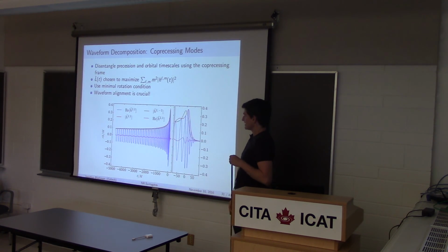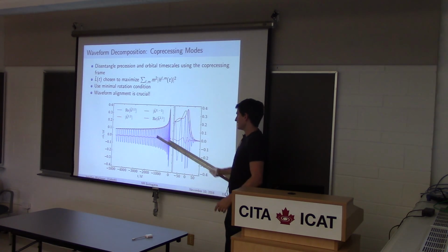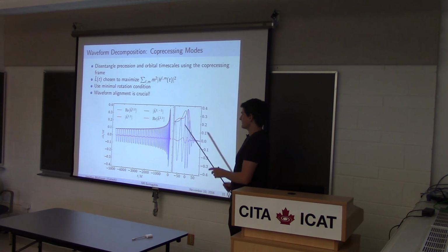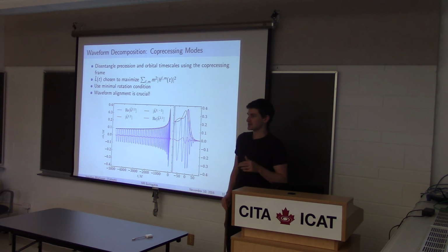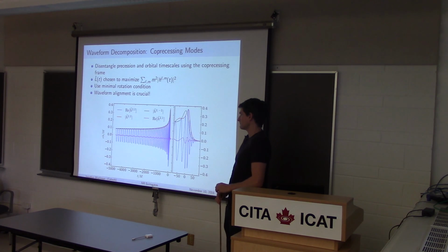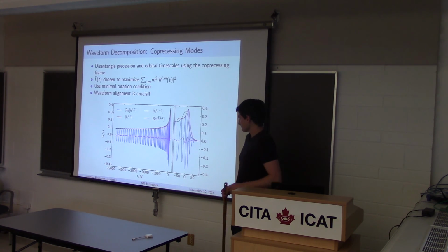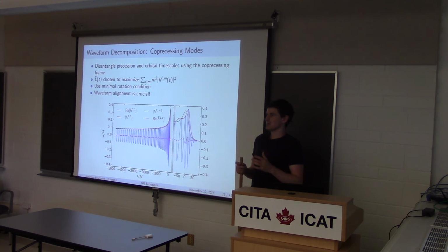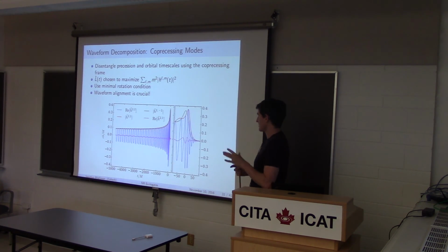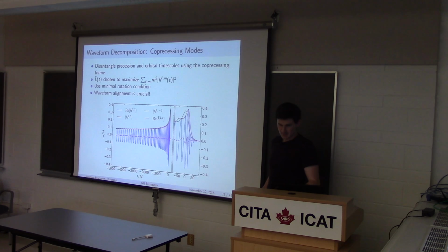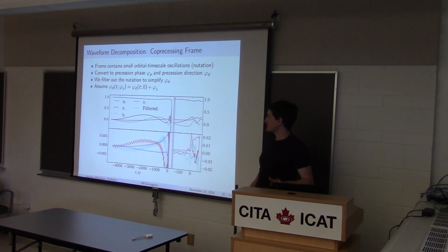smooth as well. If you take the symmetric difference, you end up with a real oscillating part. That's not actually what the purple curve is, but it looks similar to the purple curve. And what we then do is we take a Hilbert transform of that real oscillatory piece to end up with an amplitude and phase. The Hilbert transform essentially gives you the imaginary part. If you have a real sinusoid, it will give you the cosine in some sense. So we do some more data decomposition.